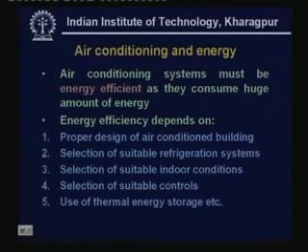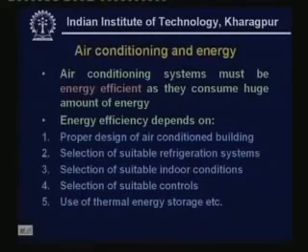In fact, this is also the reason why old buildings like old temples, forts, etc., are comfortable even in summer, because the walls are so thick that they store a lot of thermal energy and thereby provide comfort even without any artificial air conditioning system. So the thermal energy storage can be provided by way of the walls itself, or you can also have other means of providing thermal energy storage. So these are the ways by which you can control the energy consumption and improve the energy efficiency of an air conditioning system.